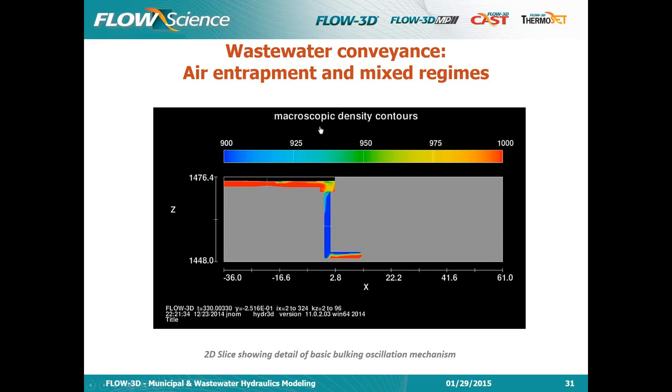So just seeing things as a 2D slice, you can see the water oscillating up and down, and the bulking. Of course, when air gets entrained into the water, the density is reduced, and that's why you get these oscillations, because the density is varying with time and oscillating with the rest of the system.